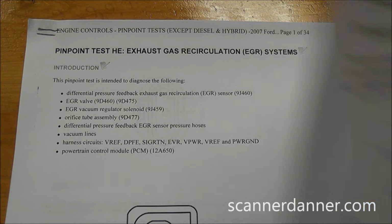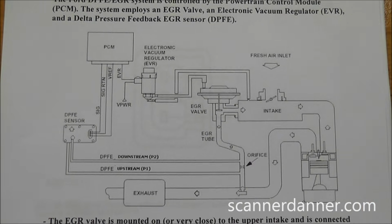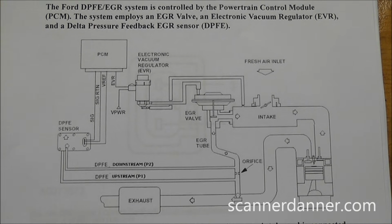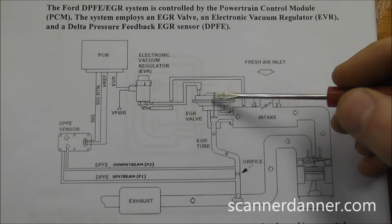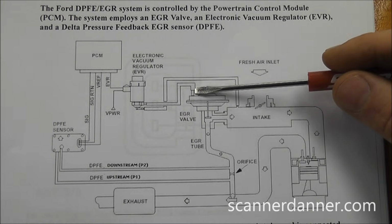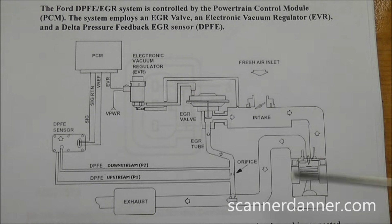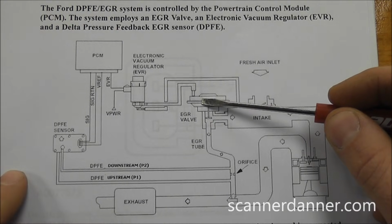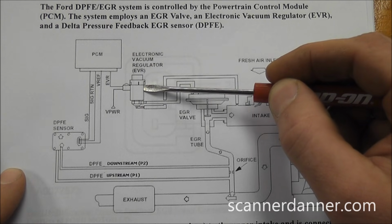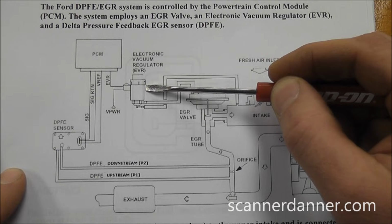So what I need to do that is talk about this design that we have on this car. Again, Google image, that's where I got this from. Looking at this system, you can see that we have a vacuum controlled EGR valve right here. That vacuum comes into this location, the valve lifts, and we get exhaust flow into the intake. That EGR valve lift or control or vacuum is controlled by a computer controlled solenoid. It's called an EVR solenoid, EGR vacuum regulator solenoid.